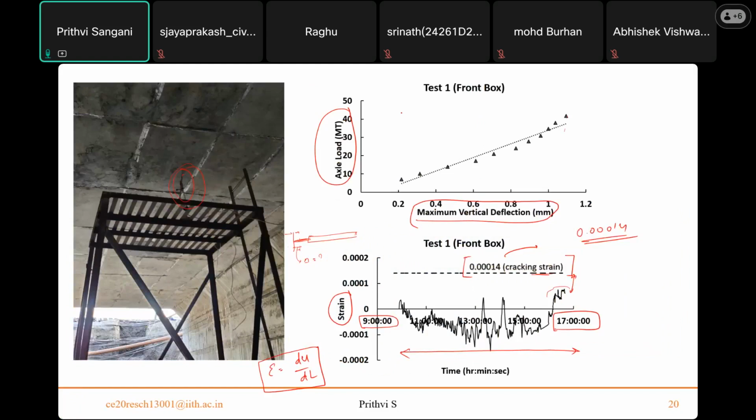At the same time, we also used the data from the strain gauges and the LVDTs, the displacements, to check whether the load had cracked the cross section, or whether there was any spalling. Fortunately, we never saw any cracks or any abnormal displacements. You can see it's almost 1 mm only; it did not go even beyond 1.5 mm.